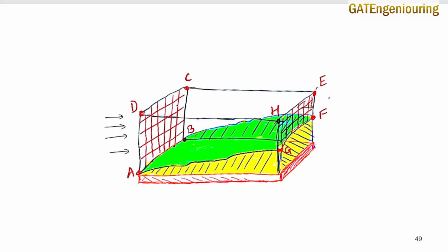Okay, so this was the area, but as soon as it touches the flat plate here, you can see that the boundary layer formation starts and its thickness increases continuously like this. So what will happen? Whatever mass is entering through this particular face should be exiting from this one also in the same amount, but that does not happen. Mass should be conserved here, but because of the boundary layer formation it's not happening. You can see that the area is decreasing here.